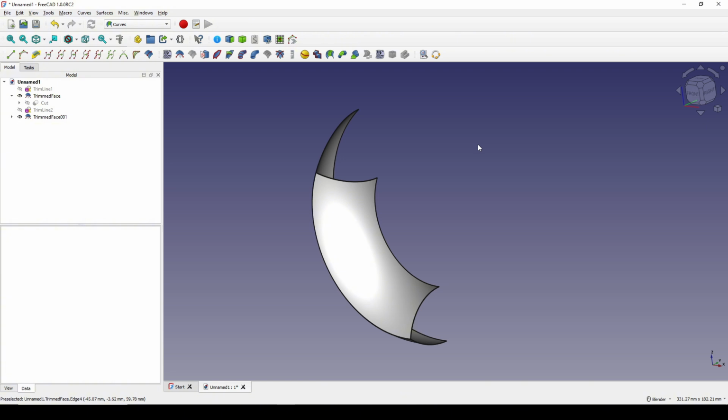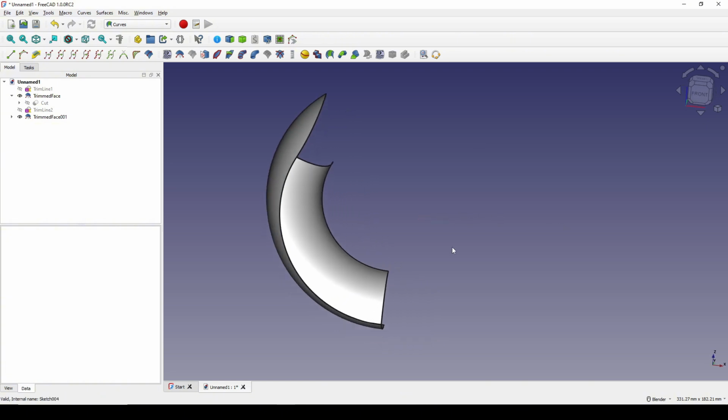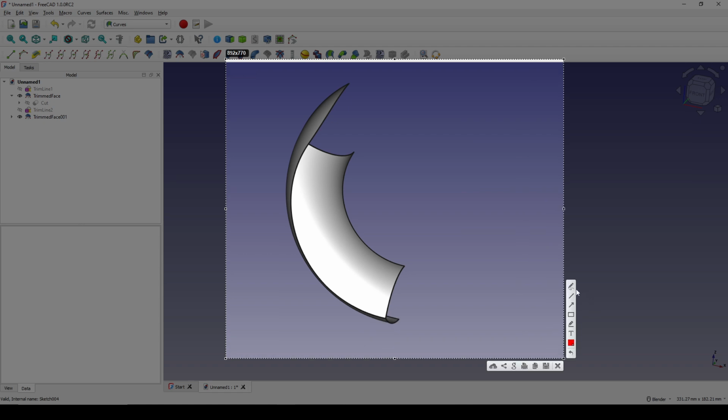The next thing I need to do is I will create a half of an ellipse like this. Okay, and I will extrude this ellipse to about here to create a surface. And from this surface, I will create a line connecting here and another plane curve connecting here. And later I will calculate to fill in the surface in between.